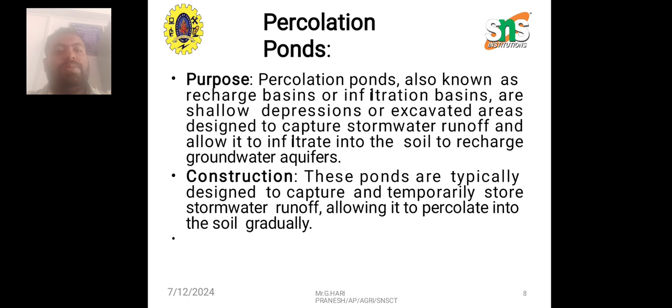Next is percolation ponds. Percolation ponds, also known as recharge basins or infiltration basins, are shallow depressions or excavated areas designed to capture stormwater runoff and allow it to infiltrate into the soil to recharge groundwater aquifers. Construction: these ponds are typically designed to capture and temporarily store stormwater runoff, allowing it to percolate into the soil gradually.